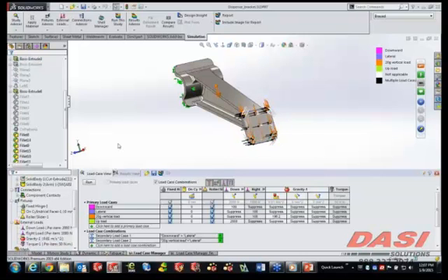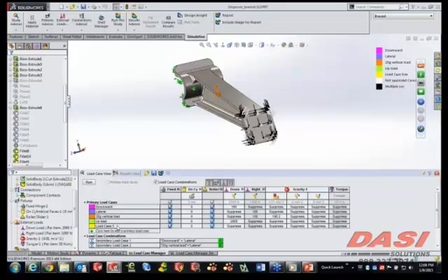What those settings are for each study is not always the most easy thing to look at. And how you can switch them for different scenarios is also difficult, because we're changing those settings per tab. Well, here in this load case manager, we can simply create different load cases. In those, we can choose to suppress or activate different restraints, as well as the loads, whether they're suppressed or on, and what the value of that load happens to be for that particular load case. It's as easy as clicking here to add a new one.